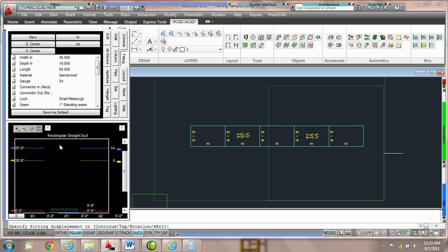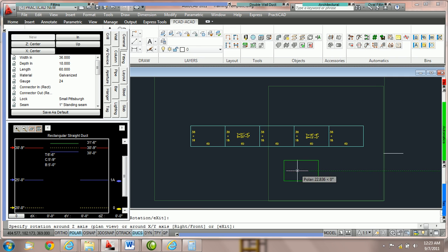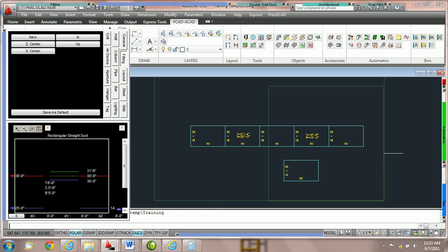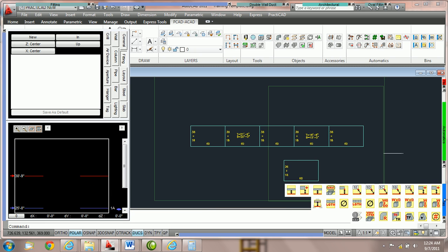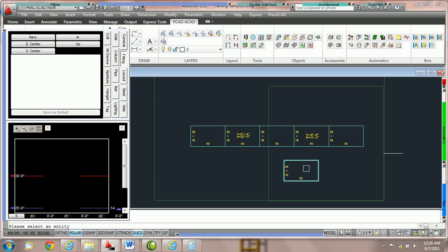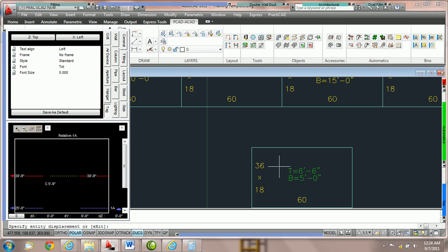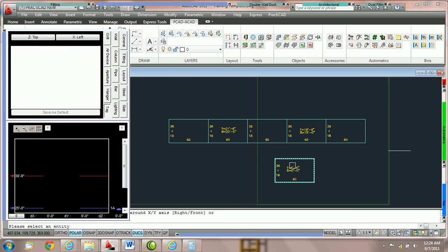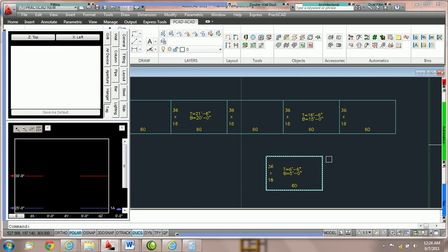And now I have a new relative bottom. So now when I say, let's put this bottom at 5 foot, it means 5 foot above whatever my relative bottom is. And that happens to be 25 foot. So you can see it's at 30 foot. So when I place it here, I put it right on top. Once again, if I'm over the 1A section, going to give it a 1A tag. And I would continue to do this for as many different slab heights as we need. So this is how to work with multiple relative bottoms.